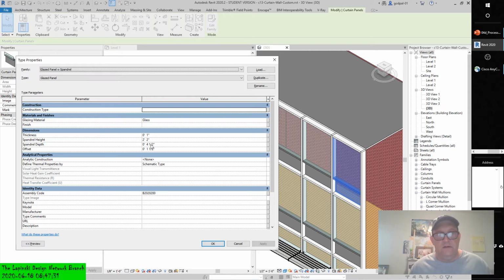And it also has that ability in the ceiling and wall sandwich. So that depth and those two dimensions can be created in a single panel family. The spandrel height is a type property of the custom panel family. Standard mullions are applied to the wall.